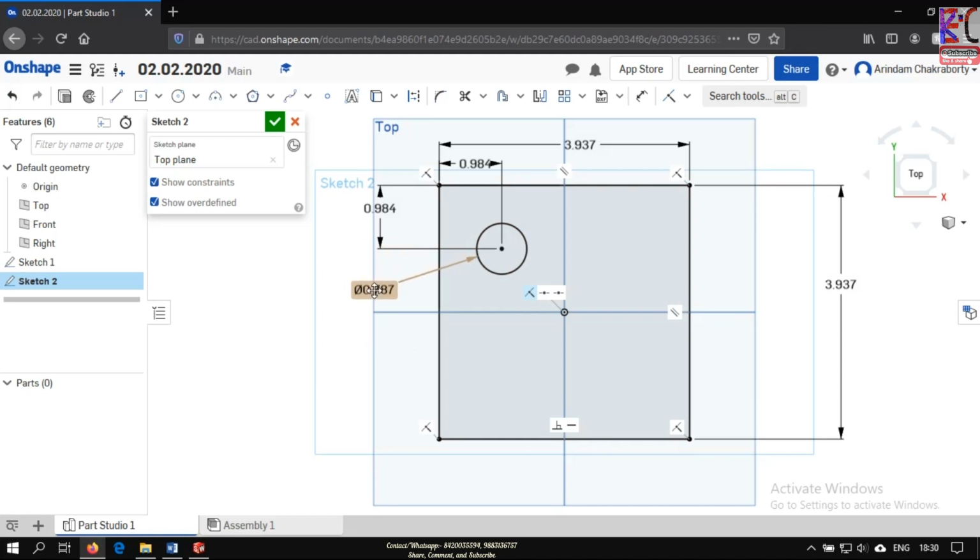Let us do this so it looks organized. What you need is a rectangle over here, so one thing we can use is the mirror action. We've heard about the mirror action. Let us try it. When you select the mirror action, it asks to select a mirror line. That means they are asking which axis it will be mirrored about. I'll select this mirror line. Now select the entity to be mirrored. They are asking what I need to mirror. I'm selecting this one.